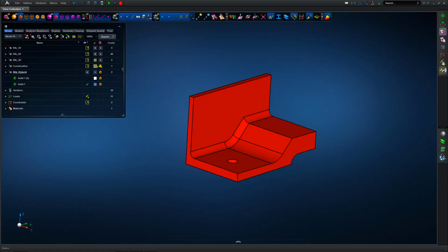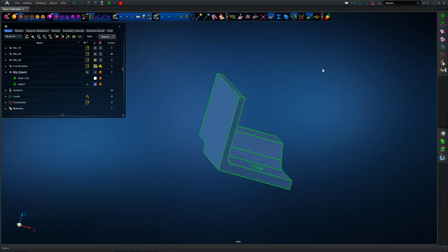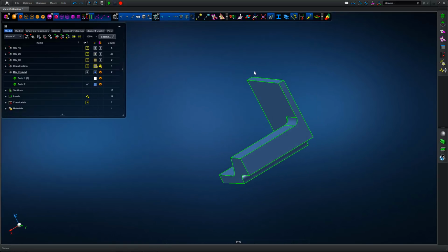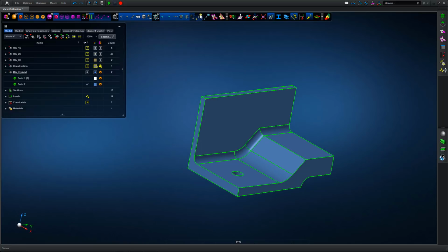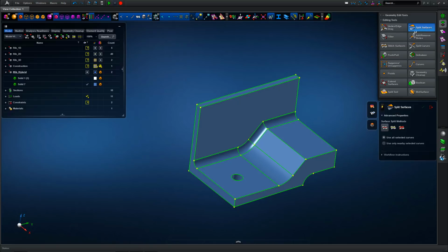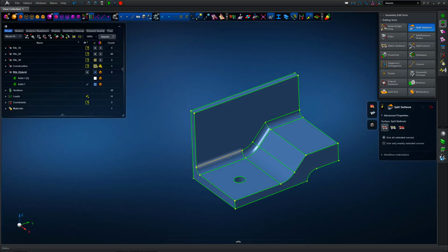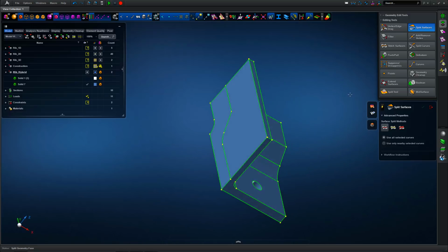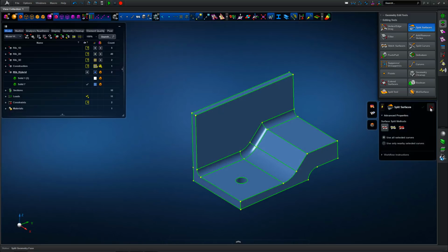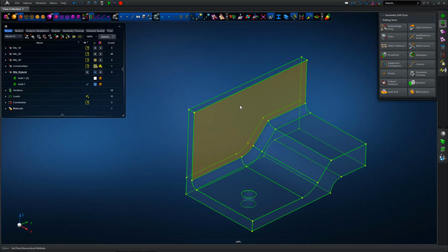So there's a tool within Apex which colours the underlying geometric definition based on whether it can be hex meshed. So we turned that on, and it showed the overall structure shown as red, which means it can't be hex meshed, and the hex mesh tool, if we tried to use it, would say sorry, it's not appropriate for this level of geometry. So we're going to make some splits in this underlying CAD definition, or 3D definition first of all. So we're going to split across the back face so we can chop out the fillet region to hopefully give us hex meshable geometry or mappable geometry.